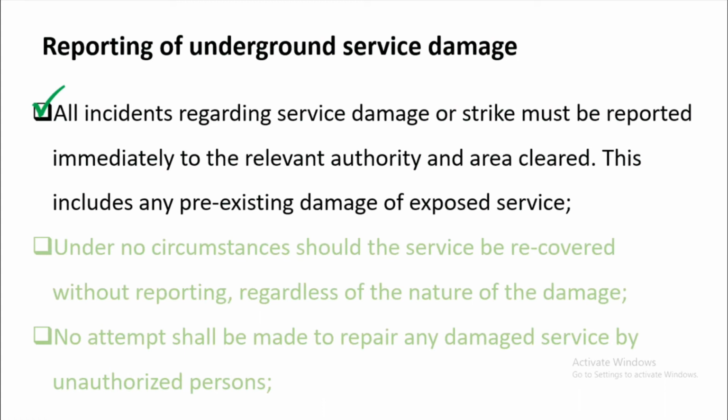Even if you did not damage the existing services, but you found that there is damage, report it also, so that you will be excused. You will not be blamed that this utility was damaged by your team. So immediately inform the utility services that you found the underground services already damaged when you were conducting excavation in that location.